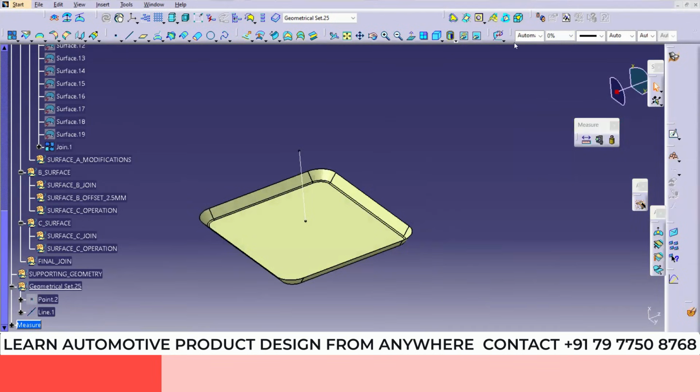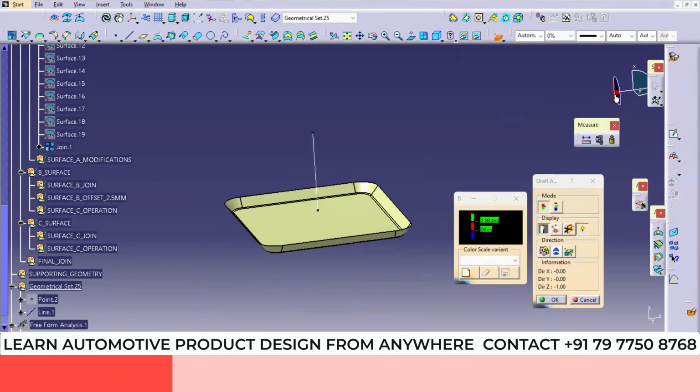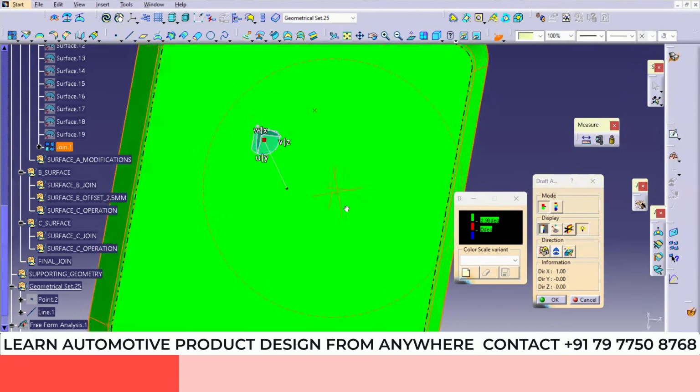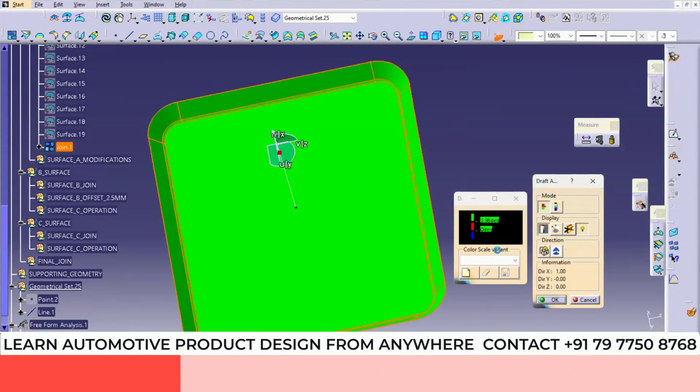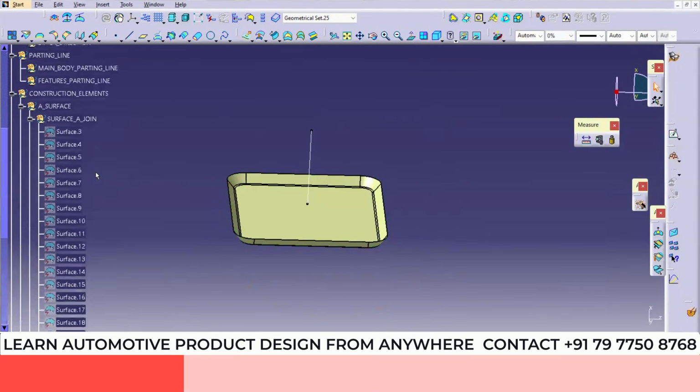Okay, so I'll check the draft analysis. So you can change the material mode now. Okay, and here I'll select draft analysis and at 3 degrees we'll check. Okay, and select this and reverse. You can see the complete surface is clearing. Okay, so this tooling direction is okay, no problem. Okay, and then hide this. So now quickly you can check all these things.